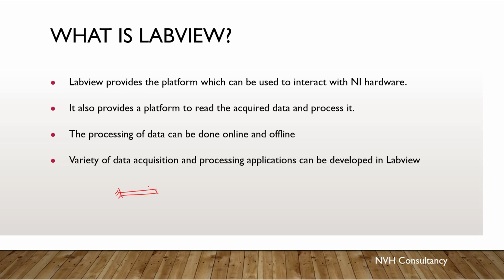So what you will do is you will install an accelerometer over here. Okay, this is the accelerometer, and this is connected to your NI9234. So this is your NI9234 system. Okay, it's a small box basically with 4 channels on it. So you will be connecting the accelerometer through a BNC connector to the NI9234.